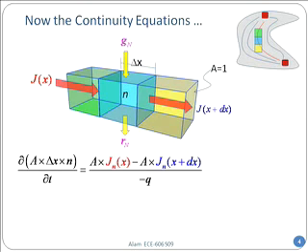So G sub n and R sub n represent electron generation and electron recombination, through trap-assisted recombination or direct recombination, that type of thing. And so all you have to do is again multiply with the volume and the Gn. What is that? That's the number per centimeter cube per second. So that's the generation rate and correspondingly the recombination rate.